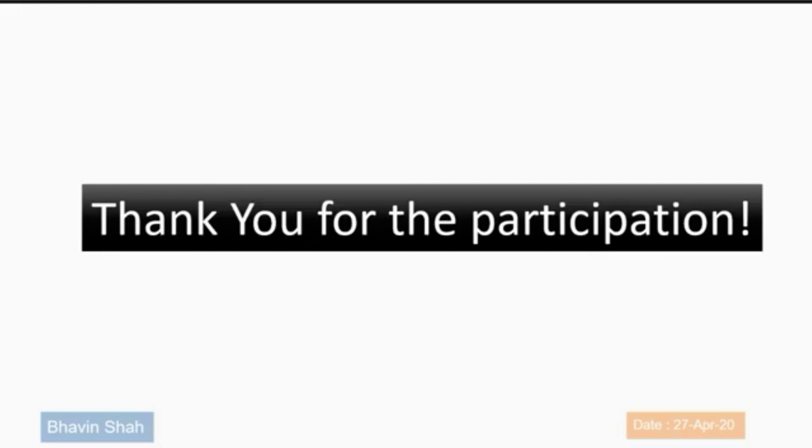Okay, I think it is Shubham who is asking that the IS code has no clause for the pushover analysis. You are absolutely right. Till today, the IS code doesn't have any specific clause for pushover analysis. But whatever we have discussed right now, when we talk about IS 1893 Part 4 for the industrial structures, we have discussed the non-linear time history analysis. For that, we will have to go for the pushover analysis only.